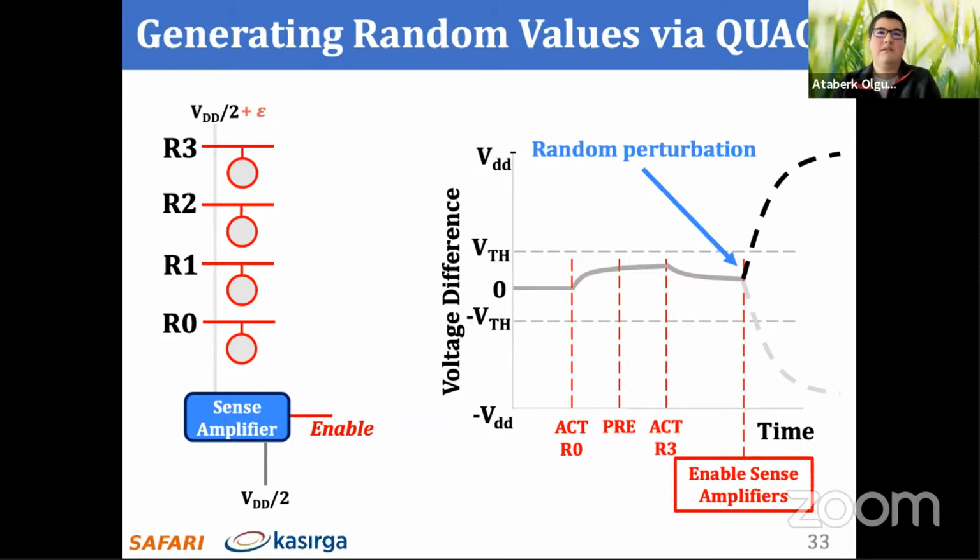Assuming this is the reason why we get random numbers, the obvious method that you can develop to get a higher throughput is something that would keep the bit line voltage below these sensing thresholds, and then just amplify the voltage at that point.